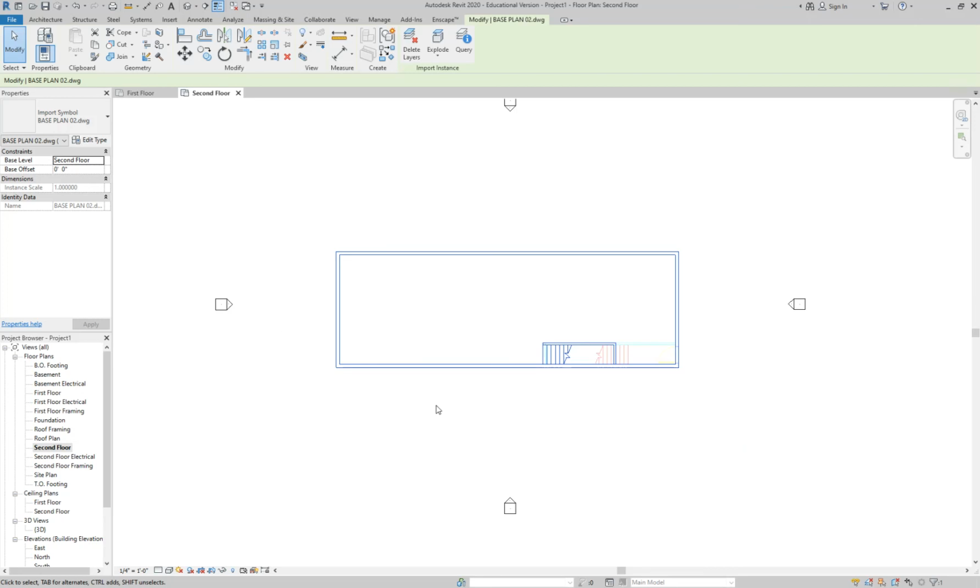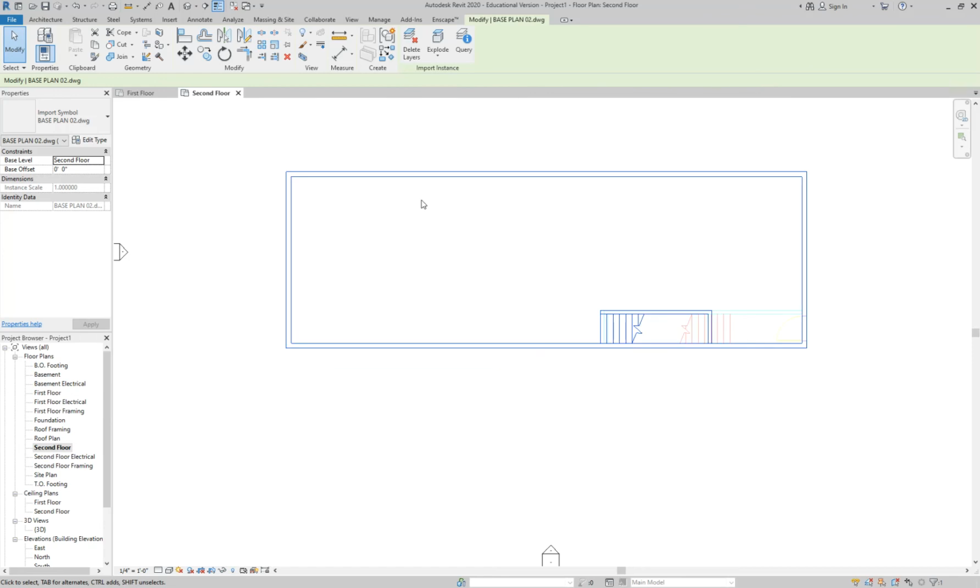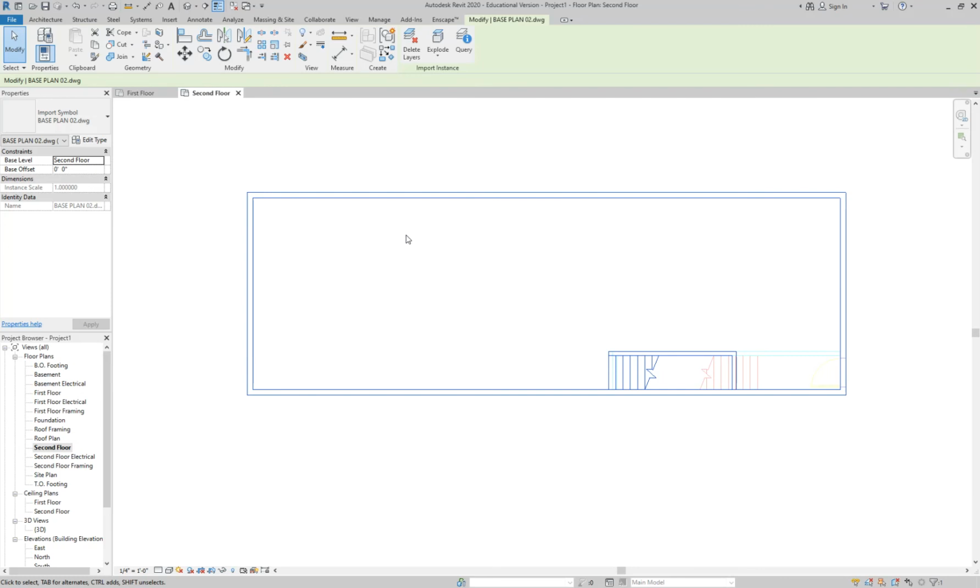Your graphic card might be having a hard time, so get close to it and click it, and if it doesn't work, try it one more time. That's an intersection, that works too. So this is one command where it probably would have helped to have AutoCAD. There's a lot of AutoCAD commands that go through when to click, when to drag, when to look for all of the different endpoints and object snaps. But because they aren't used that much in Revit, I graze over them. And you guys can wait to learn more about them in CAD. Okay? Sorry, Olivia. Sorry, Nicole.